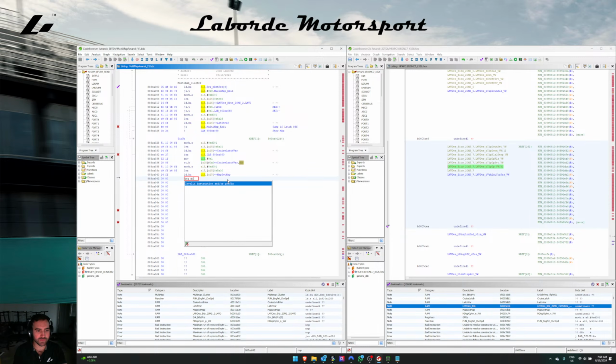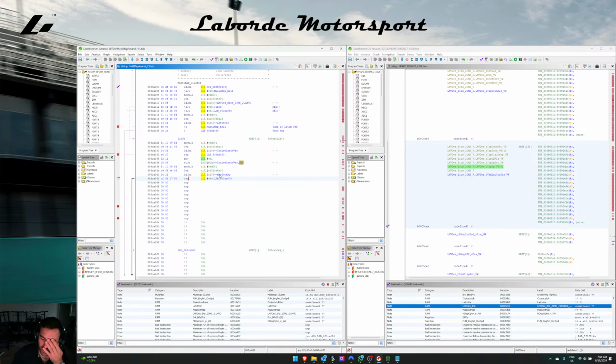jump if equals D15. You see here 0 times 0, and then we're going to go maybe 803CA070 or 803CA. Another thing as well with Tricore, with the jump equals operations, it needs to be 8 bytes. It can't be 4 bytes because that's just the way that, from what I understand, these processors pass things. If you're doing a jump equals statement, it has to be 8 bytes.